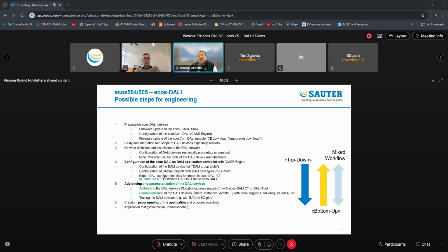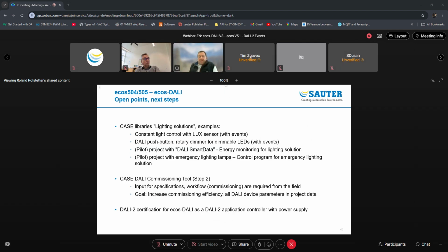However, the beauty of DALI is that all the parameters reside in the DALI devices. So normally the tools should read out the parameters on the device before they change something. Otherwise, you are brute forcing the device to be as you want it to be.